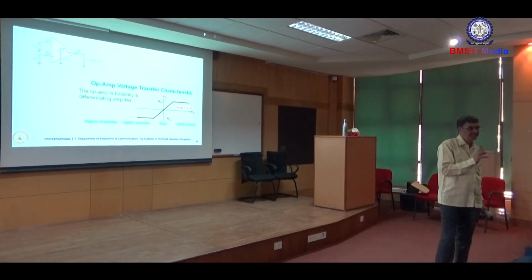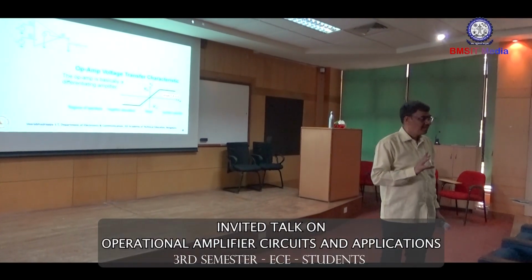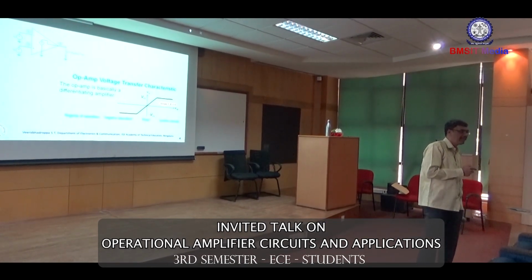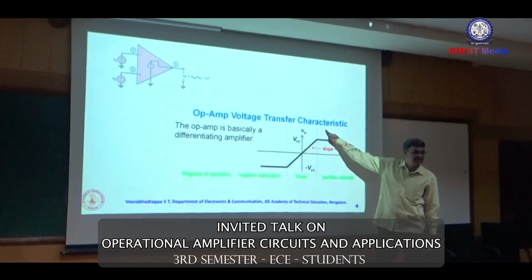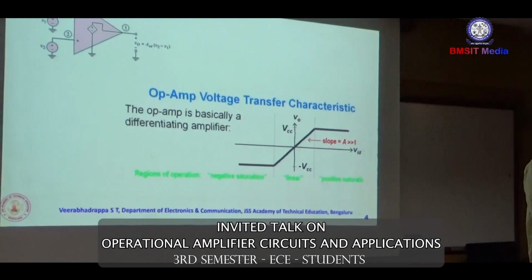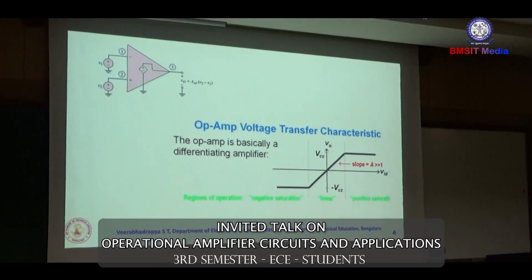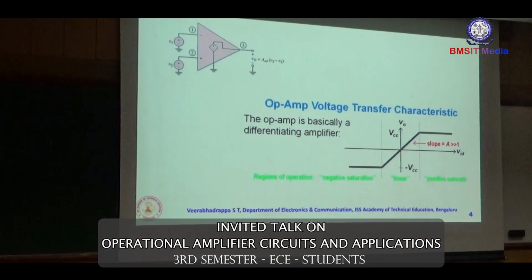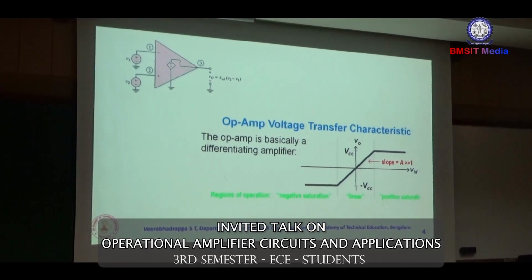That is one of the major differences between a common source amplifier with source resistance and without source resistance. That is nothing but feedback. I am introducing feedback, which is nothing but negative feedback. Due to the negative feedback, the linearity region is increased. As a result, you can even apply a few volts, and the gain of the amplifier is based on that. Then these are the output voltage characteristics. This is a very, very important concept you should remember. The whole course, module 4 and module 5, mainly depends on this concept.